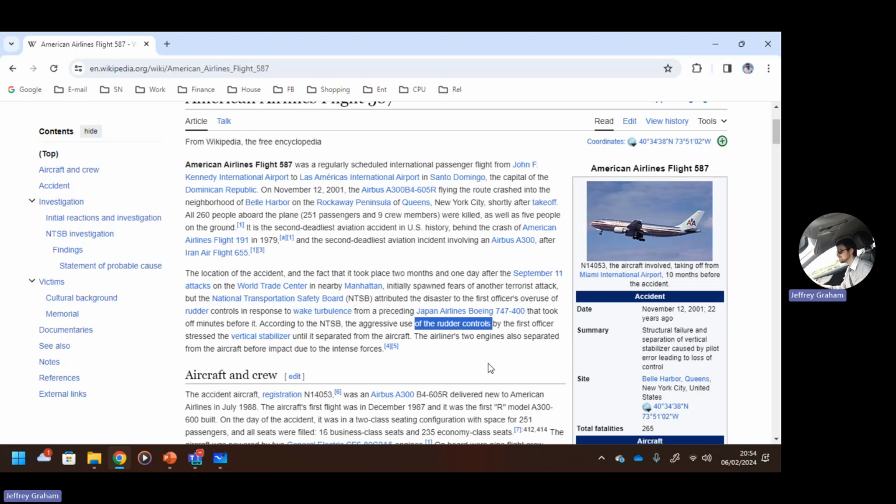As the pilot keeps going left, right with the rudder pedals, it keeps increasing the energy in the rudder system and eventually overstresses the vertical stabilizer. So in this particular instance, it was a pilot error, but obviously the fact he flew into wake turbulence demonstrates the seriousness of this. Rudder snaps off, the tail section snaps off. Obviously, you'll see later on exactly why, but it becomes uncontrollable. And unfortunately, this particular incident ends in disaster. Right, so this is the one that springs immediately into mind.